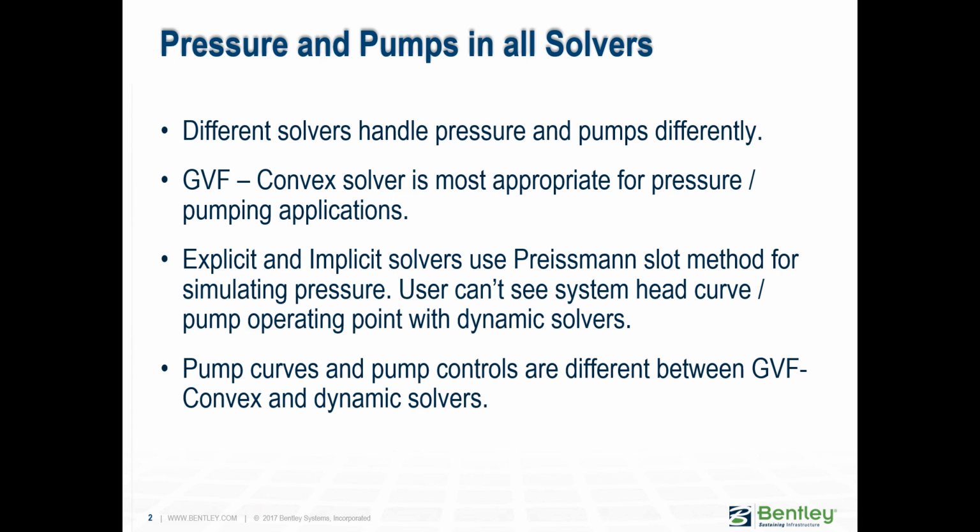If you're using SewerGEMS, you will notice that the different solvers within SewerGEMS handle pressure and pumps differently. We went over this in some detail, but we'll focus now on just the pressure part. Our recommendation, if you're doing a lot of pressure, booster stations, pump stations, grinder pumps, is that you stick with the GVF-Convex solver, which is the one found in SewerCAD, because it is the most appropriate for pressure applications. That is because it uses a true pressure engine, which is the same found in WaterCAD and SewerGEMS.